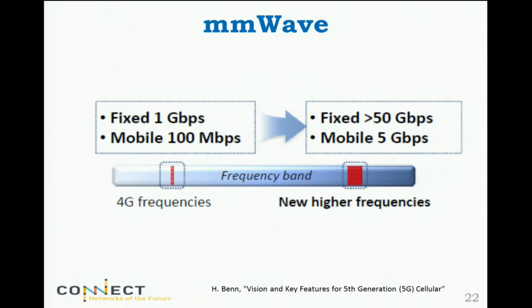Okay, so there is millimeter wave, where you can enable very high data rates. Why? Because you have a lot of band available, simply, right? You can have a few gigahertz instead of maybe tens or maybe 100 megahertz as you have today in lower bands. You multiply that by 10, and in the Shannon equation, bandwidth times logarithm of something goes up linearly. Not so true, as you know, because the noise is also going to increase, but up to some point you get a pretty good increase, right?